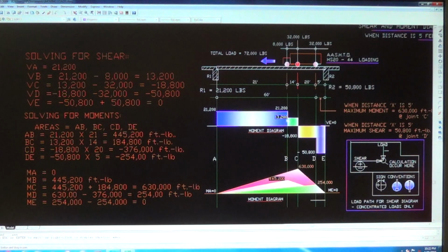Okay, the shear at C, the 13,000 will travel. Since there's no load here, it's a horizontal line. From that point there, you draw up to that line there, meeting again, following the path, to meet that load there coming down, which is 32,000, and what is that? It's coming down negative, right? So this is still positive. So shear at C now is the 13,000 minus that load coming down there. Minus 13,000 becomes minus. Since 32 is greater than 13, you retain the negative sign. So 18,000